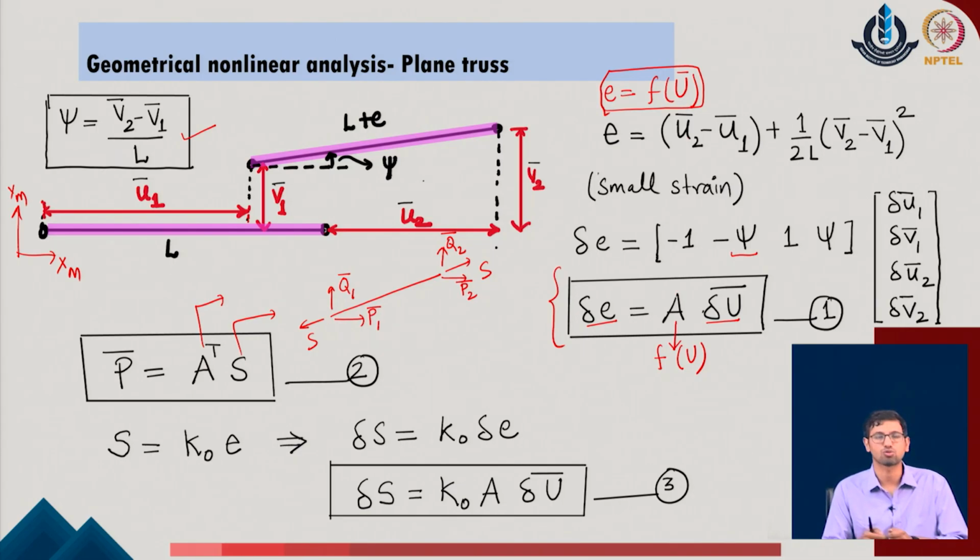In a truss member there is only one axial force, so we connect it with a simple row vector like this. But where there is more than one force in the system, like in the beam problem we will see later on, A can also become a general matrix.